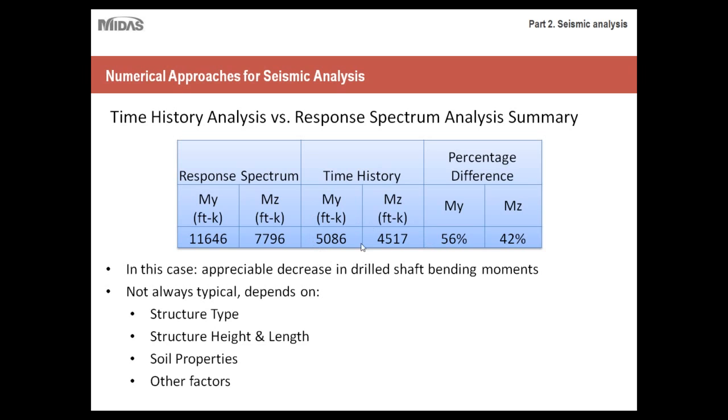In other words, if you use your time history analysis, then you can say with great confidence that, because of these calculations, because of the simulation that I just ran, these will be the critical moments. You'd be able to have a design that's more optimized, that's more cost effective. So with time history analysis, you'd be able to have maybe more competitive bids, because depending on your project, a calculation difference such as this could help you create a design that could save maybe thousands of dollars even. But it really depends on the project itself. Just keep in mind that with response spectrum analysis, although it's easier to run, it is more conservative. Whereas with time history analysis, it takes longer to run.